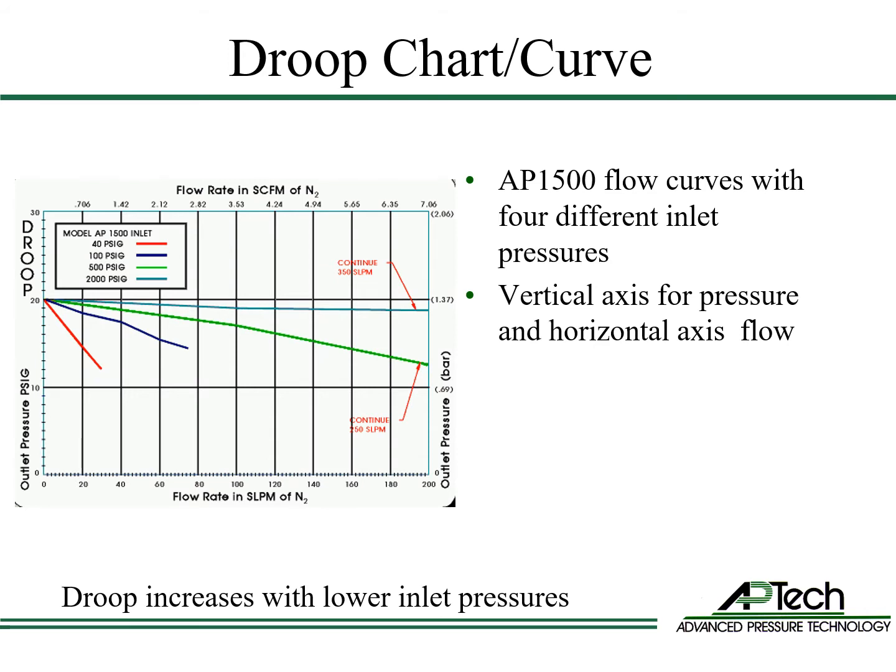When sizing a source regulator for gases, it is generally advised to use a flow curve with the intended cylinder change pressure for the inlet pressure. Using an inlet pressure of 200 to 300 psi, for example, as opposed to full cylinder pressure, will allow the user to select the correct regulator.